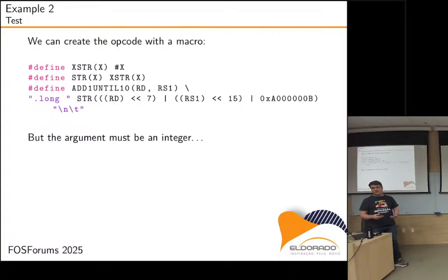So we start by writing the test. It's usually a good idea to test things, see if they are broken before you try to fix them. So first we will write a RISC-V program that will execute the instruction. We'll have an illegal instruction trap, and then we will start implementing the instruction itself. The compiler does not know about this instruction, we just made it for this presentation.